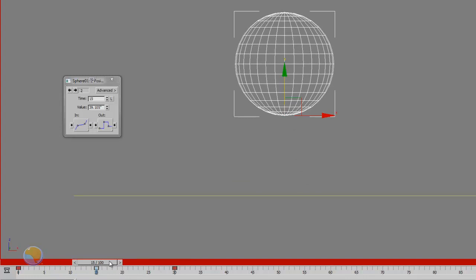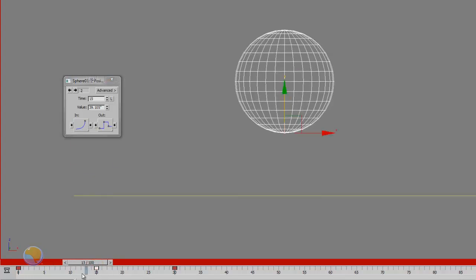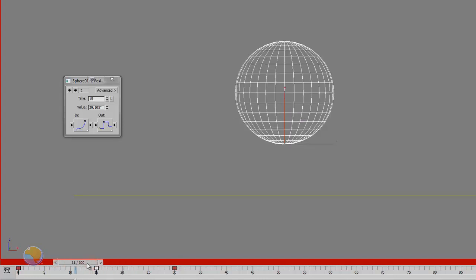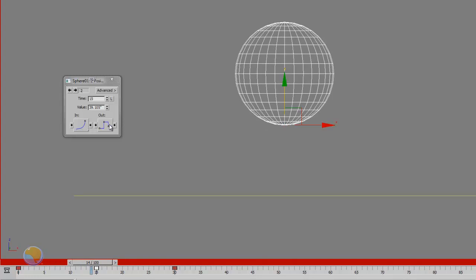Okay, so you can have lots of different iterations of animation styles using all these different types of tangents, and this really makes your animation a little more powerful and a little more expressive, and it also saves a lot of time and saves a lot of keyframes. As you can see, if I had to go in and keyframe all this movement of keeping it slow or fast in and out of these keyframes, I would have to add a lot more keyframes in here to control that motion. But now it's all built into those tangents.